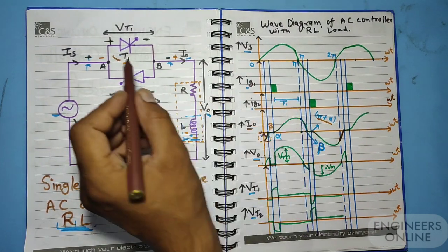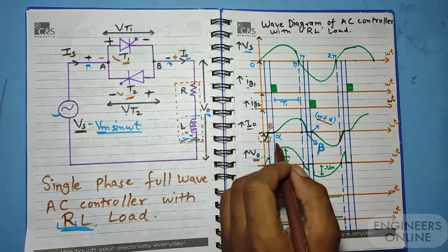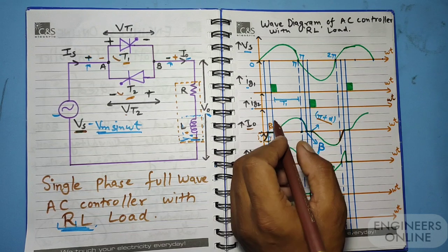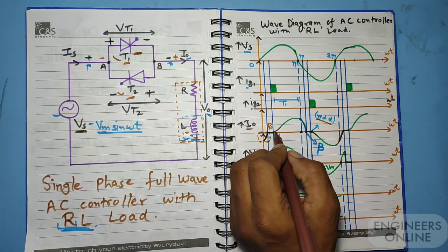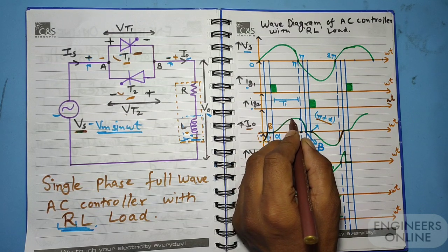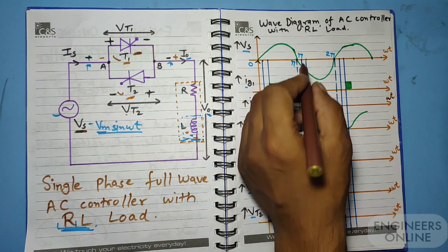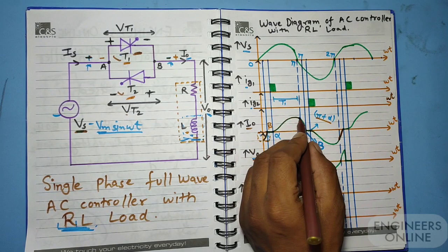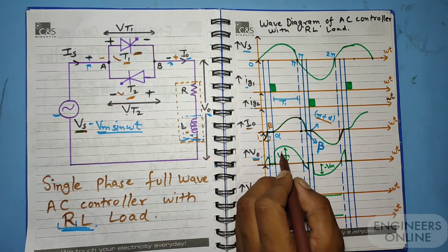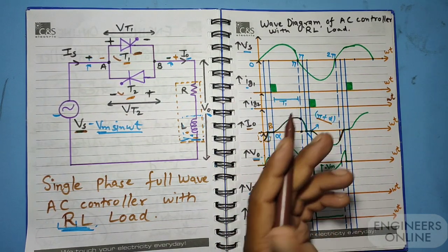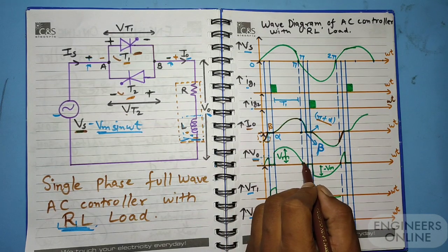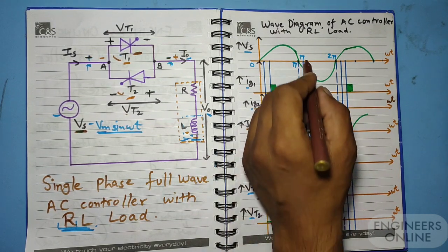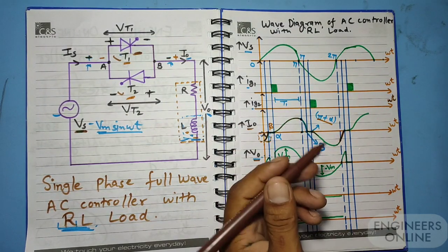After giving the triggering pulse to thyristor 1, current starts to flow in the circuit, as after triggering it starts to conduct. The current will increase, and up to the point where the voltage source is 0, the current did not reach the 0 value. Why it didn't go to 0, I'll explain to you. And the potential drop also goes to 0 with this voltage source.